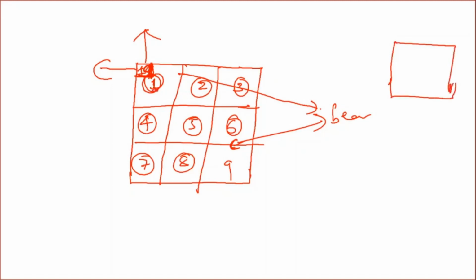whenever I apply the load on the slab, these corners try to lift like this. The corners try to rotate, the corner tries to lift. Because of that rotation, torsion will be developed. To resist this torsion, we again have to provide reinforcement. To provide that reinforcement at the corners, you have to form a square with the side of 0.2 Lx.